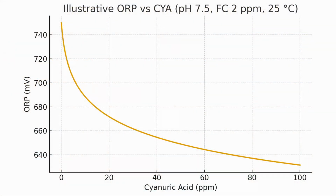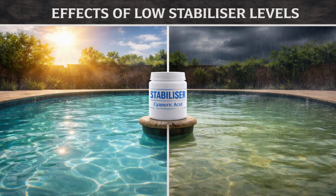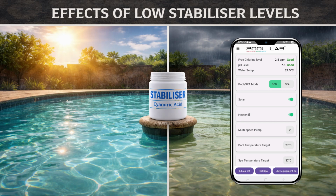ORP probes also have an inverse correlation between the ORP millivolt value and the cyanuric stabilizer level in the pool. An overchlorination event is likely with probe systems if stabilizer levels change, as they do during a season. Probe manufacturers seek to mitigate this by restricting the use of stabilizer, but this causes wild swings in chlorine levels and an inability to keep up with chlorine demand. Pool Lab will record accurate free chlorine values regardless of the cyanuric acid level.